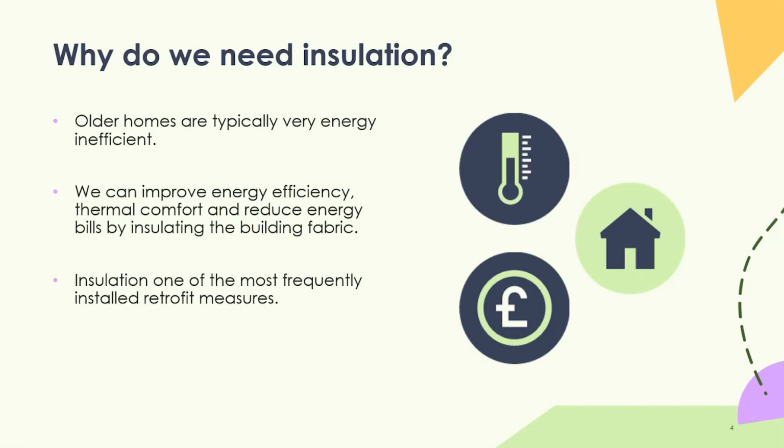So basically we're talking about typically older homes, pre-1920s homes, generally solid wall design without any kind of insulation facility within the walls. Generally, the ventilation is done through drafts and air bricks that are provided within the actual fabric of the building. And typically those homes were heated with open fires, and they were providing a draft to draw in fresh air through the rest of the house.